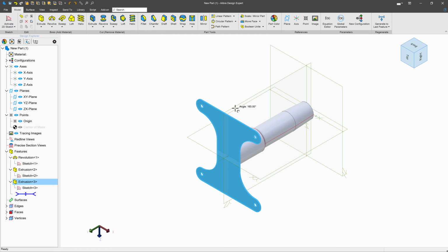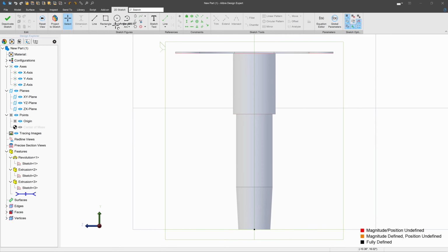I'll add a bottom part now. And I'll create a line. And I'll make sure that my line is symmetric. So I'll choose this axis and these endpoints, and now my line will stay symmetric around the origin. And we'll give this, from end to end, a length of 10. Make sure that it's coincident upon that line there.